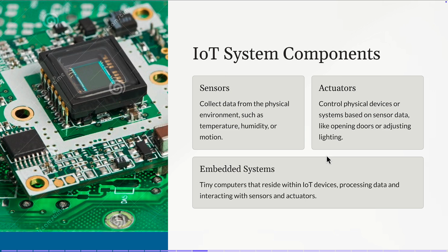So we can turn it on and off. I can make it work 1 second, off another second, because these events usually come in a continuous manner. If I turn it on and off at different intervals, this is what we call the duty cycle. For example, if I work 1 second and go into sleep mode 1 second, this is a 50% duty cycle. Still, it's not efficient. Sometimes we can sleep for 1 minute and wake up for 1 second, so I can make the duty cycle 1%. The duty cycle is defined by how often the event may happen.